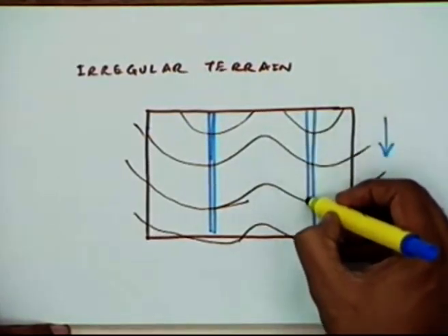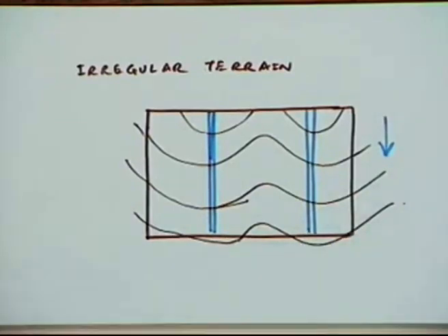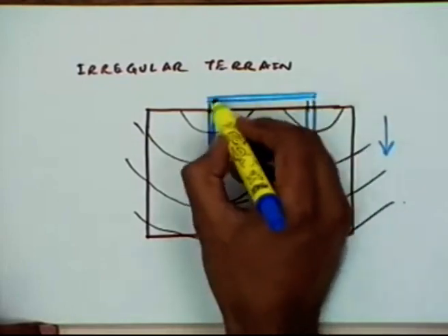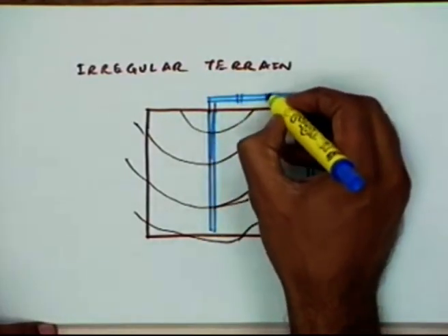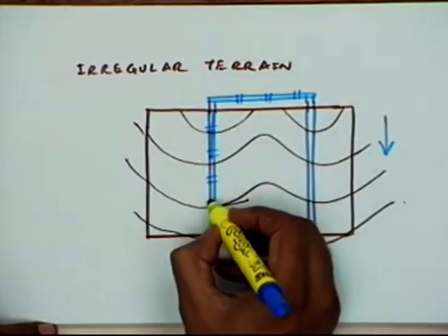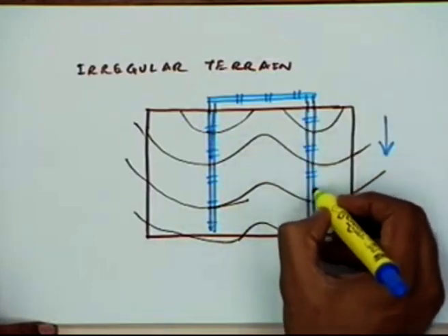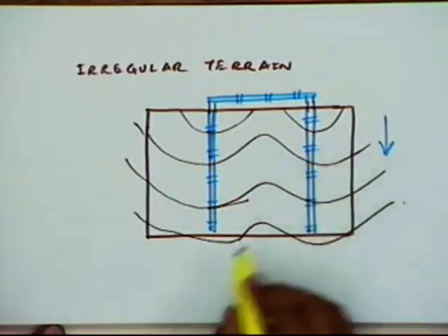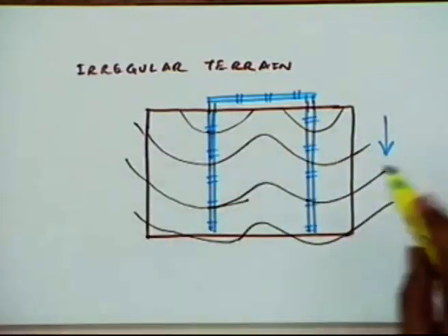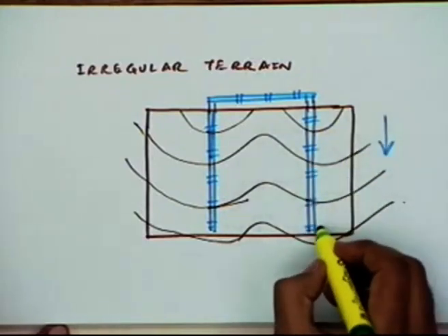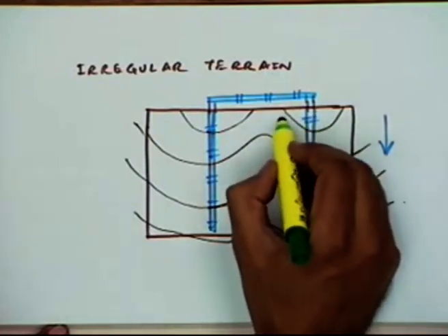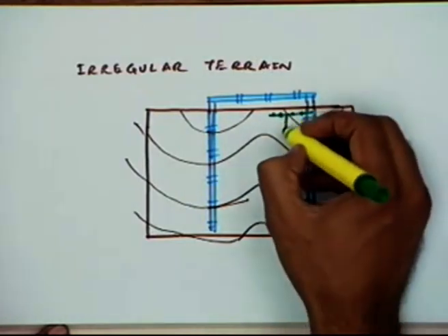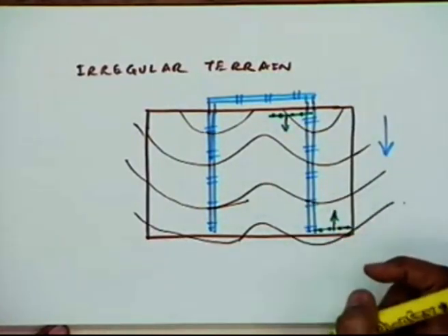Now, if we situate the main line on the ridge, and this main line, again the source, there are 2 main lines which you have laid. All these are the main line sections. This is the nomenclature which I am using for depicting the main line, as we have done earlier also. On these main lines, if you have laid the main line in such a fashion, to operate the laterals, the laterals can be operated in this manner, that you have these two laterals, this moving in this direction and this one moving in this direction.